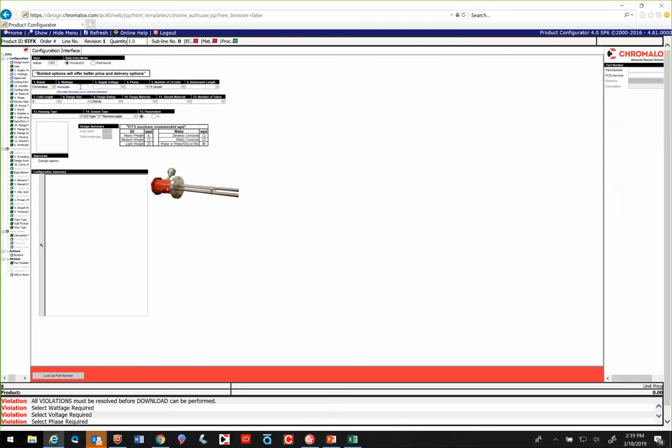It won't let you. So if I go to, I'll put in 50 kW, right? You see how I just jumped back to 25? It will not let you go over that. It will not let you deviate from a catalog item. And it's important to know that because I know several people have fallen into it.